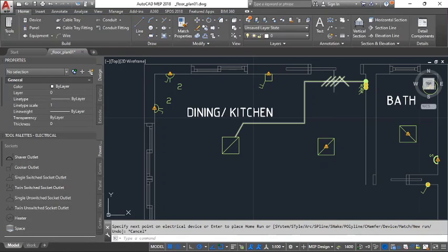Now you see these symbols are not right. It shows 3, 5, they're actually 4, and then 1 at 90 degrees to this 4. So that is a representation of a 3-phase wiring, and what we need is single phase. So we basically should have one hot, one neutral, and one earth.